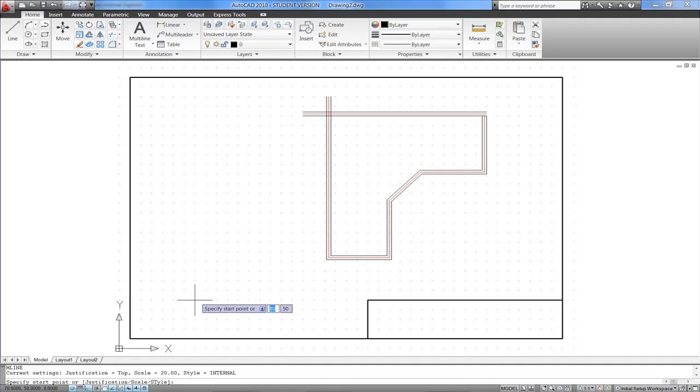And I think I want to switch off OSnap for this next step. I want to be not too tidy here and not too specific in terms of sizes for my internal walls. I'm going to draw a vertical line here, horizontal, escape, spacebar, and draw another vertical line here, and finish here, escape, and that's all the multi-lines that I need.